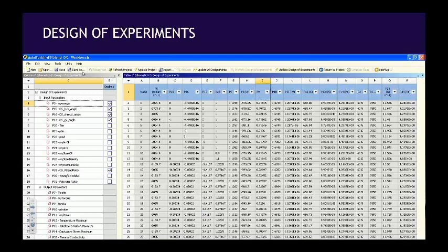What we can do then is take those wing profiles and do something called the design of experiments that was previously touched on. So what we can do is say, all right, look at my wing angle, and I want to change my wing angle and sweep it from 0 to 20 degrees. And I want to figure out where I separate, so where my max downforce figure is. So I can run through that.